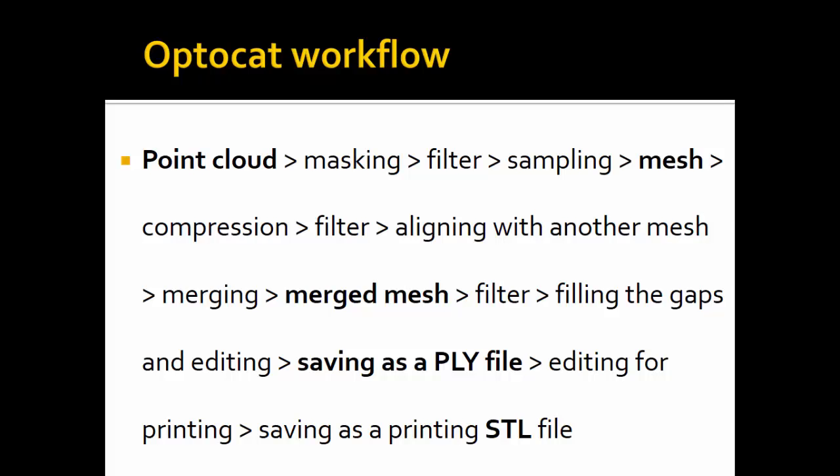Each scan is 1 million points, but I may actually be using no more than, say, a couple of hundred thousand points, and no more than that. So maybe 20% of the full point cloud. I may apply a certain filter and a certain sampling. So I may tell, for example, use only 10% of the points.